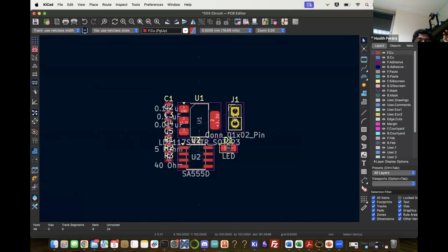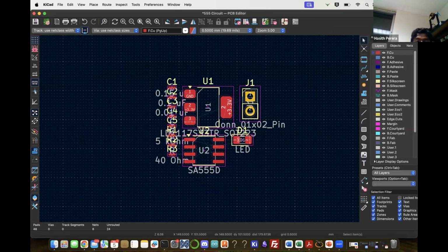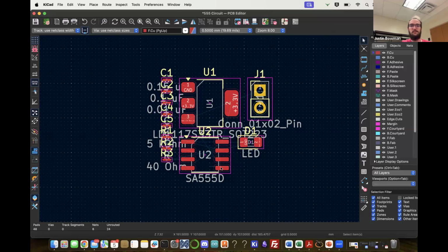Hey, Justin. Yes. Quick question. Yeah. So I have the schematic done. Okay. Values were fixed. I selected all the pads. Yes. So I flipped it to the black screen, but mine is empty. What did I do wrong? Did you click the update PCB from schematic button? Update, okay, got it. I see. And that should bring up a screen that tells you. Right. Okay, update PCB. I don't see any warnings, no errors. Right. I see. Okay, yes, thank you. Now you have all your components in a small bunch. Right. In a small bunch.